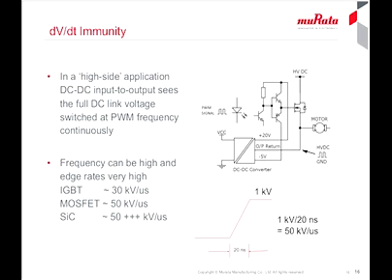In a later webinar, we will look at the different types of insulation and how well they stand up to the stress as measured by the so-called partial discharge effects, which is the slow degradation of insulation over long periods when subject to high voltages. We will show that traditional insulation, which may even be good for safety agency ratings, is not necessarily good for partial discharge performance.